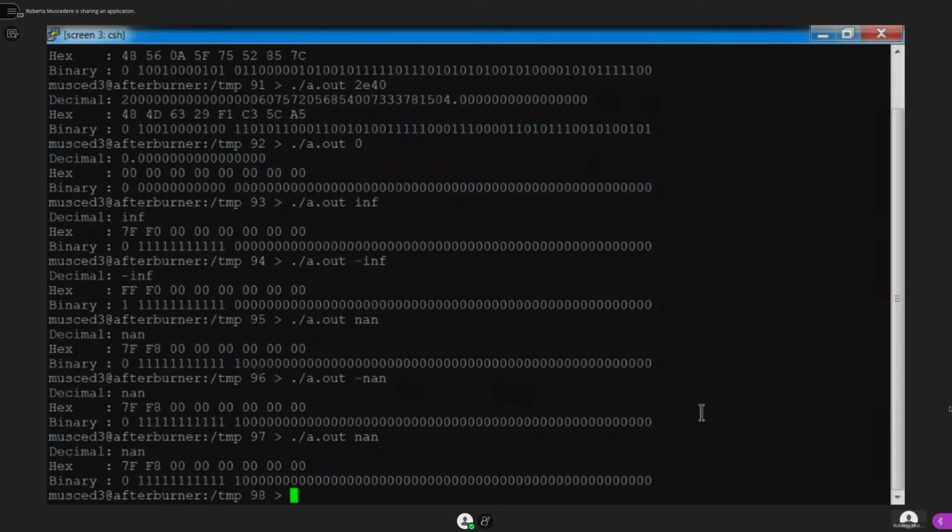We have to have these things because we're using this for real computing, things that can affect a whole bunch of things. But we do have to be aware of the limitations. So this is one way we can store it. Now, floating point comes at a relatively large cost, right? Building floating point hardware is much larger than integer hardware. When we did a ripple carry adder, there's your adder. A floating point adder involves a lot of work because of the representation of the numbers.